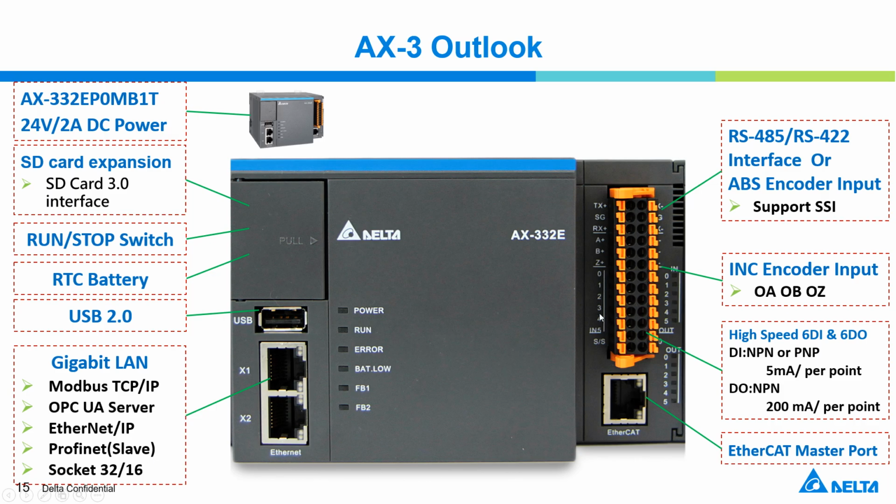And for the built-in I/O here, it can support the RS-485 and absolute encoder, but like AX8, you need to choose one of these two functions. Cannot use them at the same time together. And it also can support the incremental encoder input, and the high-speed DIDO and the EtherCAT master port.